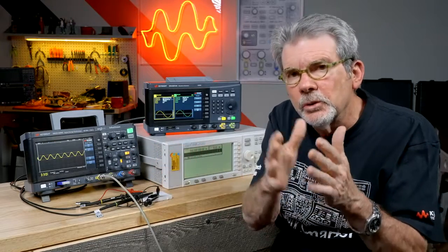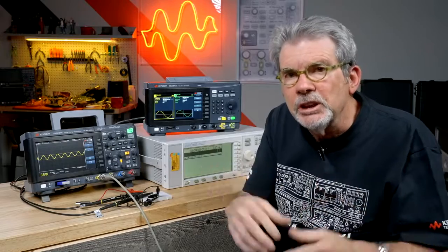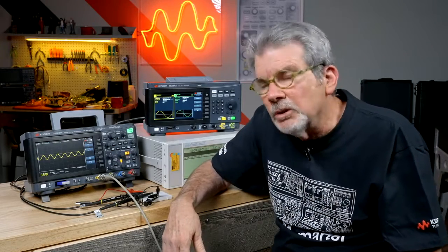Up to about the 5th harmonic is very important in order to capture the true nature of a digital pulse. So for example, let's assume your highest clock rate is 100 megahertz. I would recommend a 500 megahertz scope. If your highest clock rate is a gigahertz, then you better get at least a 5 gigahertz bandwidth scope.